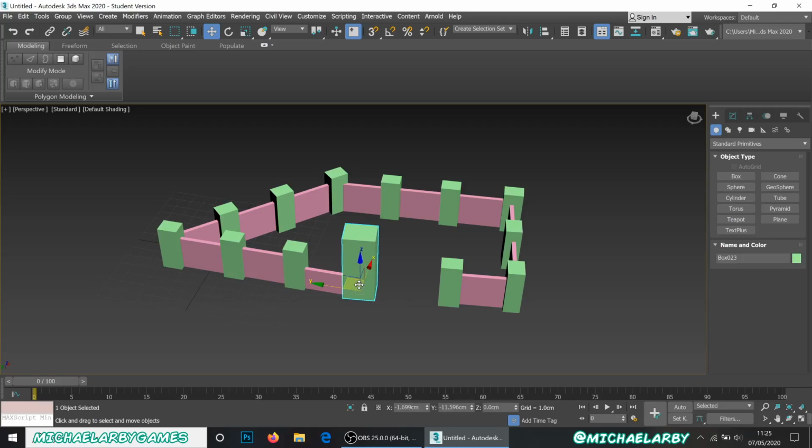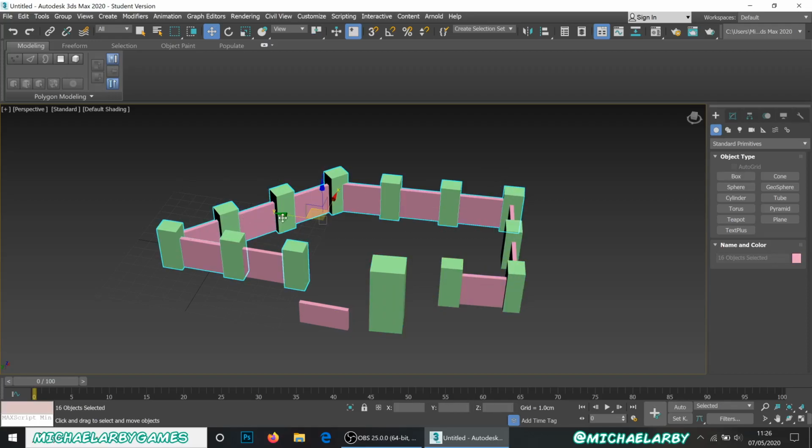Oh yeah, the other benefit, that's what I was going to say. The other benefit of this is, rather than having to texture this whole thing, all I need to do is texture this object and texture this object, and that'll give me good texture density, good texel density, and then that'll be repeated across each of these. So how the process works is, in 3D Studio Max, I'm not really actually going to assemble this whole shape in 3D Studio Max.